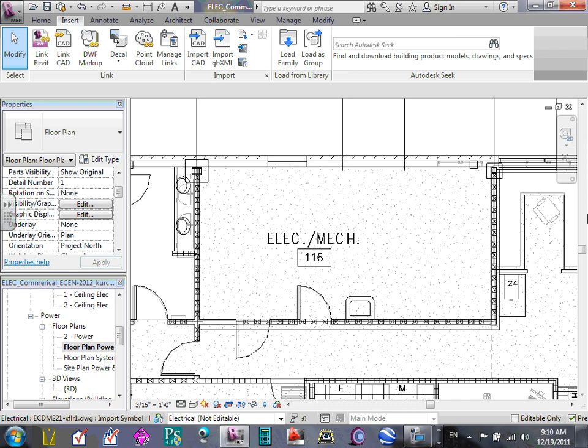Okay, just to remind you, I'm going to drop the panels now. Where am I going to drop the receptacle panels? If you have to choose, always choose an outside wall. There's a little problem though. There are some windows in this area. I have this wall here, completely continuous. Can you see this completely continuous concrete wall? That's a good wall to put my electrical equipment on.